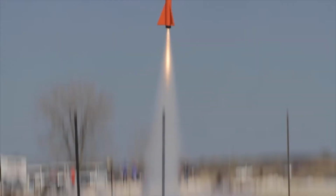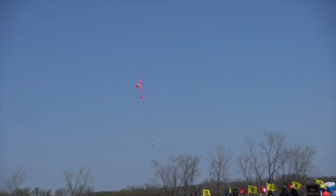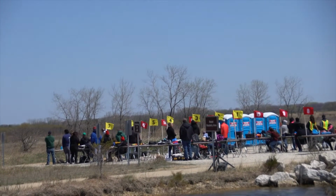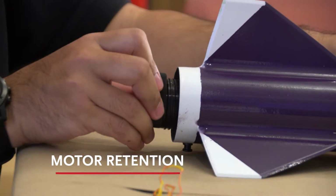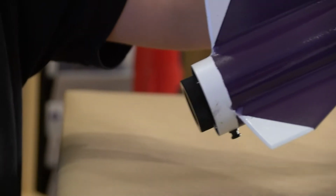After a motor's propellant and delay charge have been burned out, they ignite the deployment charge. This explosively pressurizes the interior of the rocket, forcing the sections apart and deploying the recovery system. However, if the rocket motor is not properly restrained, it will be blown out the aft end of the rocket also. Motor retention components such as rings or clips do not typically come with kits and may need to be purchased separately.